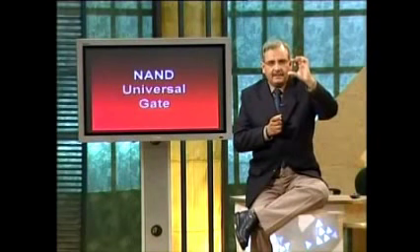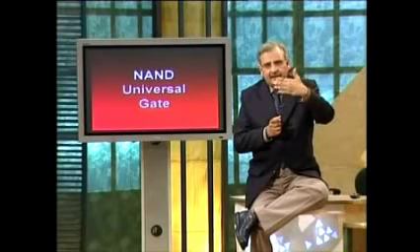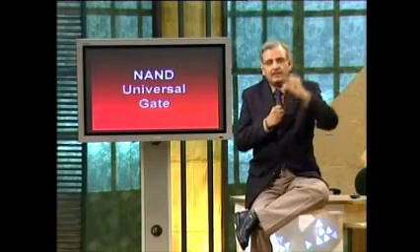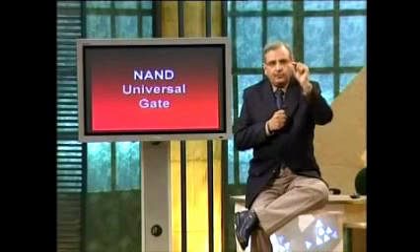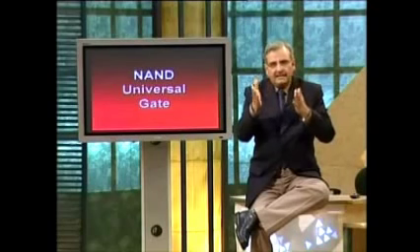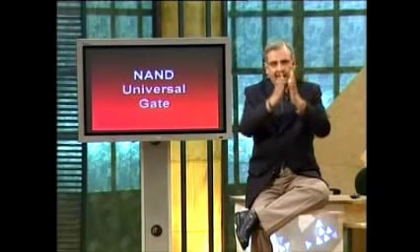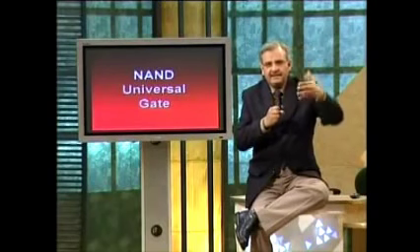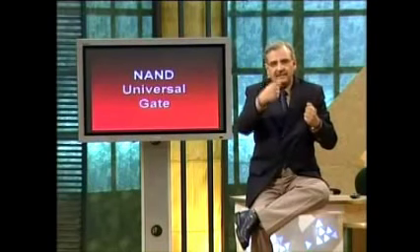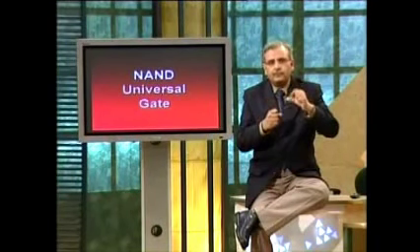If it is the AND gate symbol, what is its alternate symbol? The OR gate symbol, select that. The other thing which you need to do is to put bubbles at the inputs and the outputs where they were not there earlier. So if you consider the original AND gate symbol, it does not have bubbles at the inputs or the outputs. So when you select the alternate symbol, which is the closed V, you would put bubbles at the inputs and the outputs.